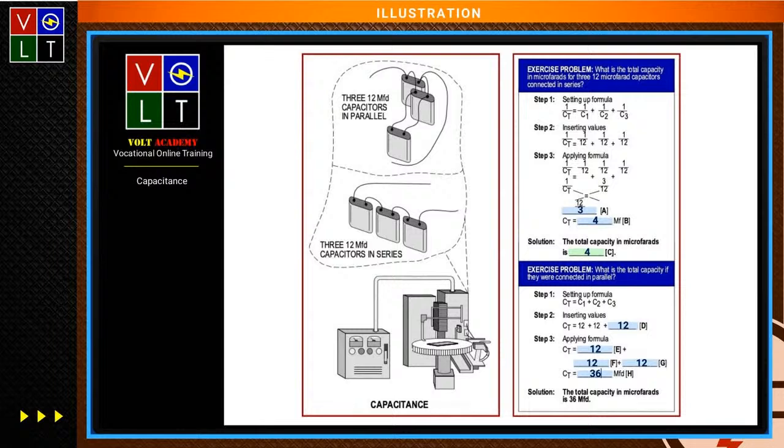We actually show you here the RPM is at 1800 RPM, I'm not going to go through the whole problem. And then when you do it at 50 hertz, it was at 1710. Okay. And we actually have that in there. Yeah, and it makes sense why the inspector had that concern, because there was some HVAC equipment, and he was like, "Are you sure you did all that calculation?" And I didn't even know, because somebody else supplies the HVAC equipment, and we just hook it up, and they're like, "Oh, you're gonna have problems here," and I didn't know.